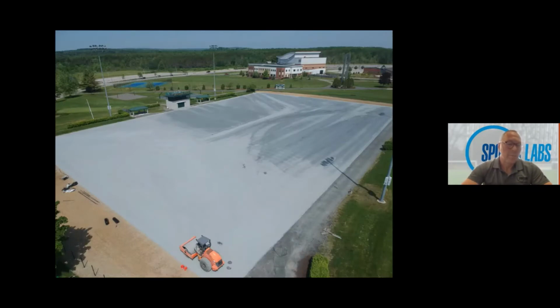Unless you've got tons of money and a site where you don't have to worry about the levels, then the subgrade and the soils that you're building your field on has got a significant bearing on what you'll subsequently superimpose on top of it. And we can't stress enough, get to know your subgrades or your soils when you're designing your base. A recipe approach is a very, very risky approach at the end of the day, and we'd stress not to go down that route if you can possibly avoid it.